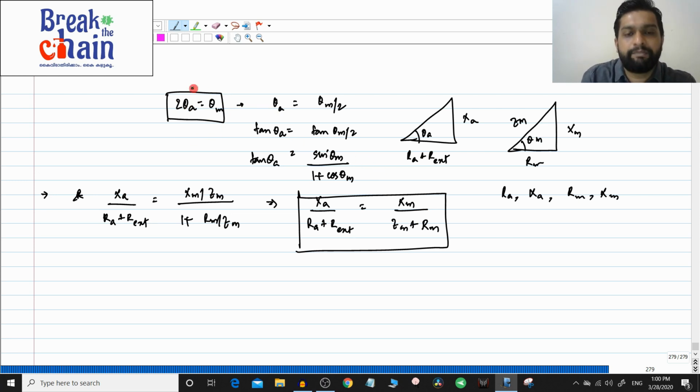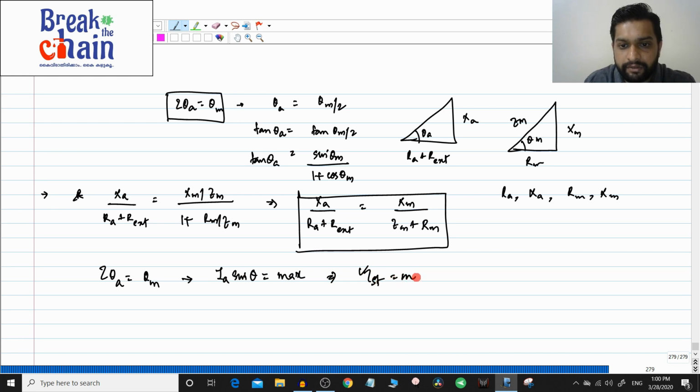Just remember this particular condition, that is 2 theta A will be equal to theta M, and this is the condition where Ia sin theta is equal to maximum. That implies starting torque will be equal to maximum. Okay. So, with this, let us conclude this video. I think I have told a lot in this video.